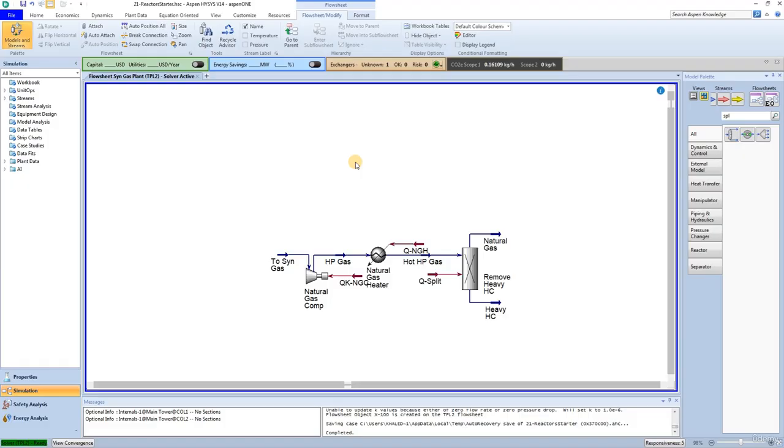Task 2. Set up reactions and reaction sets. The definition of any chemical reactions to be considered within a HYSYS flowsheet must be made in the properties environment. All tools and features needed for specifying various classes of reactions are available there. Once the reactions have been defined, specified, and properly assigned to the active fluid package, they can be used in the simulation environment. One more thing to consider: make sure any components needed for the reactions are specified in your component list. Now navigate to the properties environment.